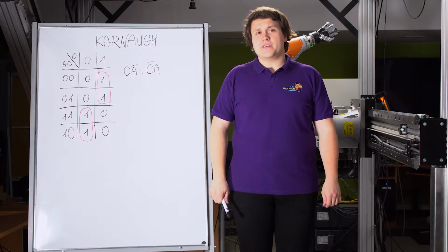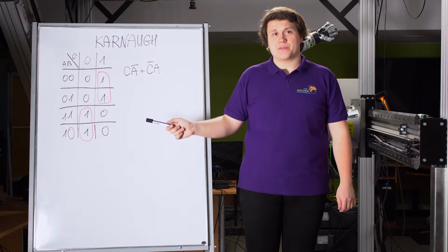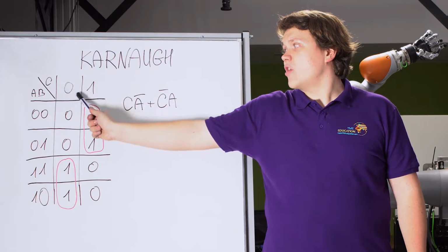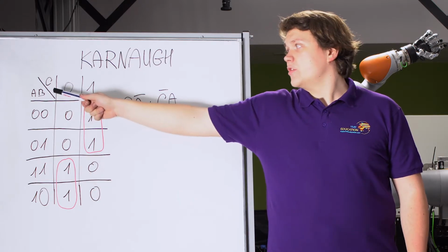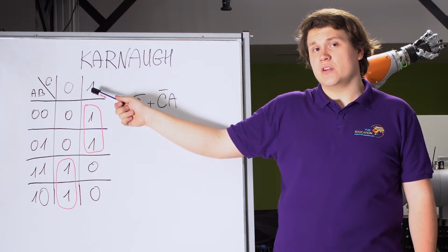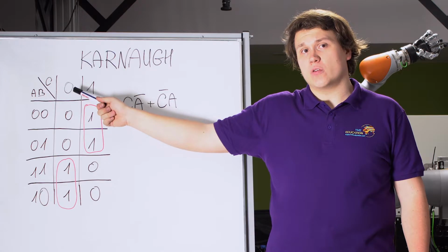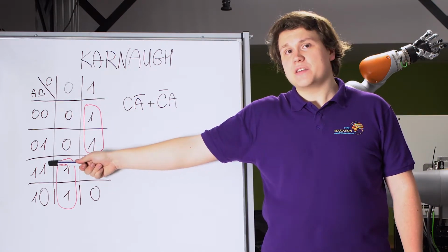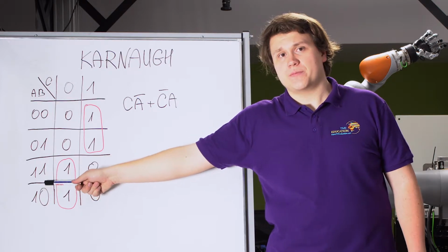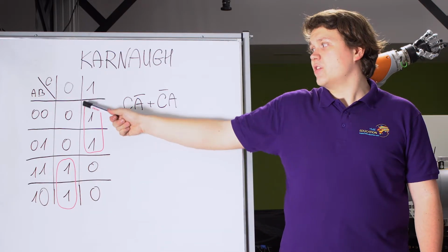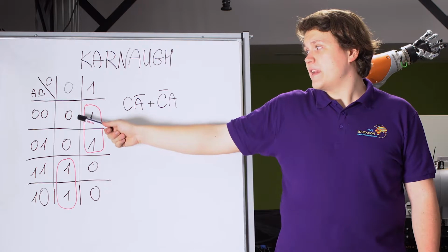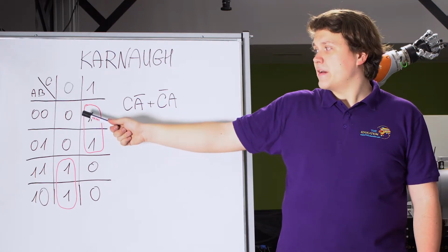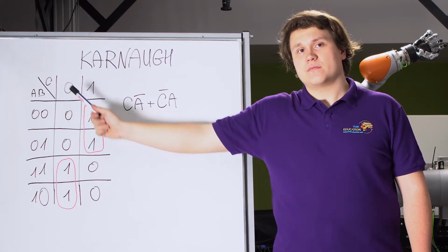We have to make a logic device performing a specified operation. In this device, we have three inputs represented in rows and columns. Rows and columns in the Karnaugh method are represented with a gray code. That means that two subsequent numbers differ only in one position. Each field of a Karnaugh board is filled with a number representing the logical state on the output with given input values.